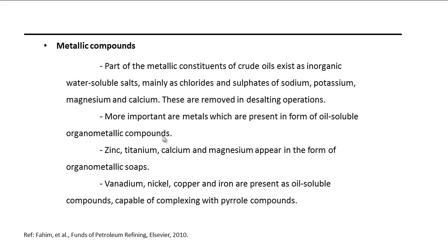In the case of oil-soluble compounds, mercury, vanadium, nickel, arsenic, and cadmium may be present in a trace amount in the crude oil. We need to have some unit to remove those. Otherwise, a very little amount of those will damage the catalyst downstream or even cause corrosion in terms of amalgam formation, and that may block the flow of the crude inside a small pipe diameter.